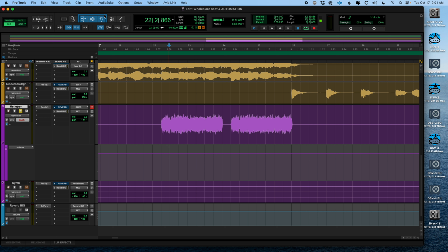If you're using the MultiTool here, which is the tool I usually use, the easy way to do it is to hold the command key, that's the control key on a PC, and see how the cursor turns into a little hand with a plus sign on it. That means add a node. These little white dots I just drew are called nodes. And once you have a few of them, you can let go of the command key so you're not adding any more. You can just click and drag.